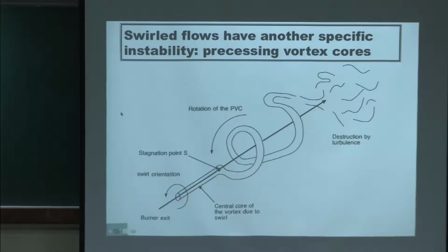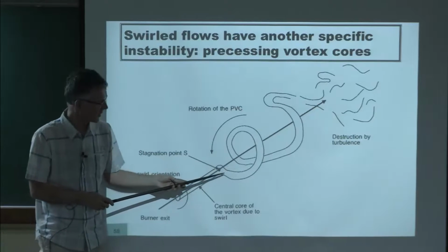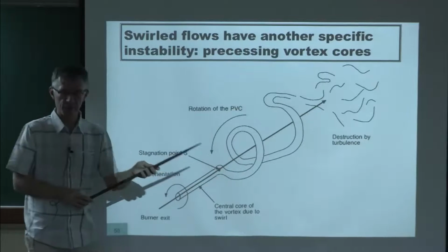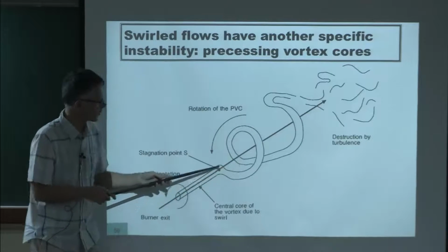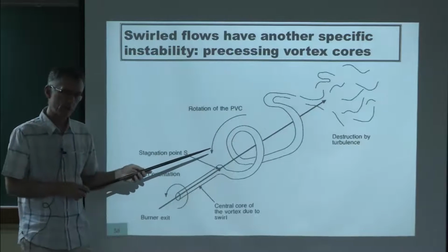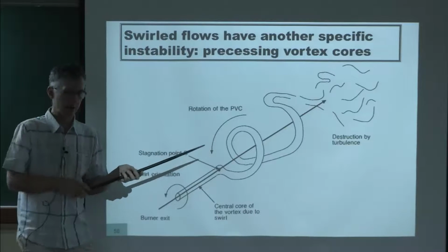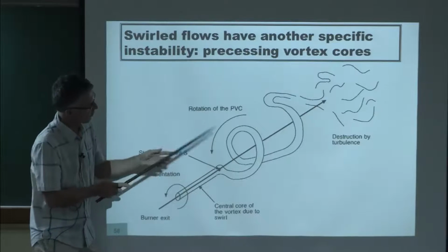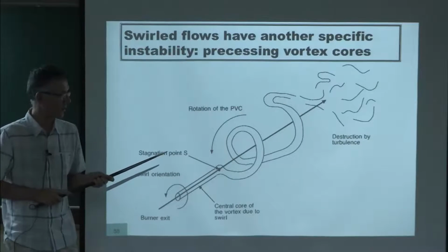In combustion, if you have not two but one swirling jet, what's happening quite often is that this thing starts precessing. And if it's precessing, what you actually see for the axis of rotation is that it will follow a spiral mode like this one. The spiral mode does not have to turn in the same direction as the mean swirl. That's where things get complicated. The flow can be turning like this, and the spiral in the other direction. It depends on the swirl intensity.